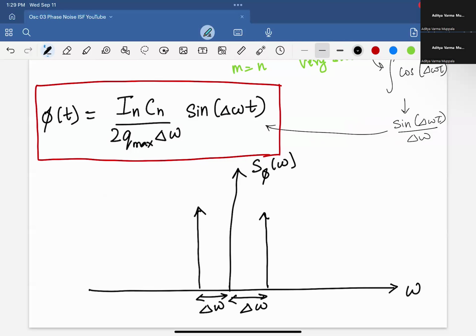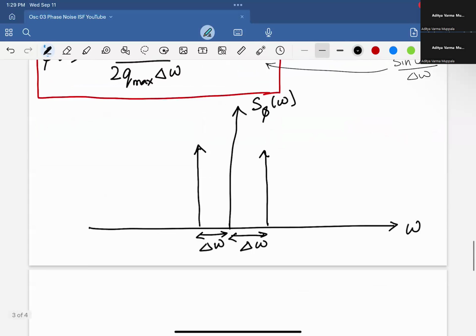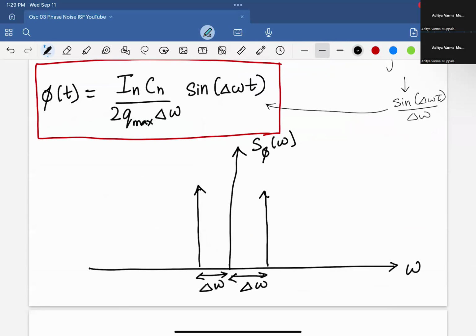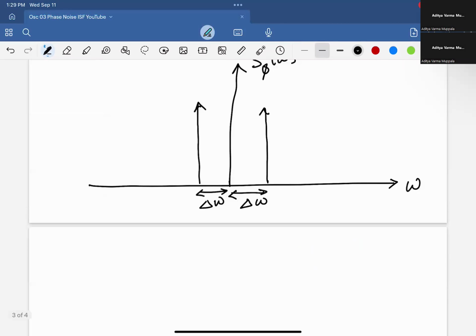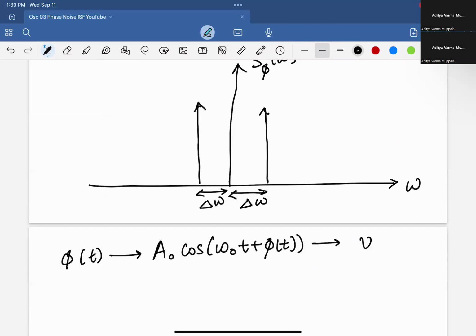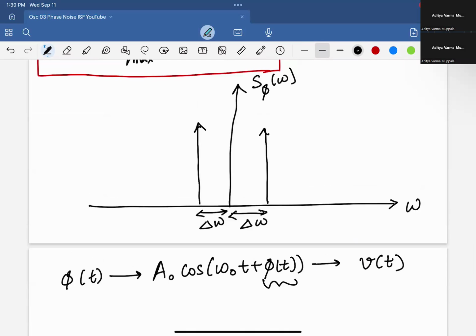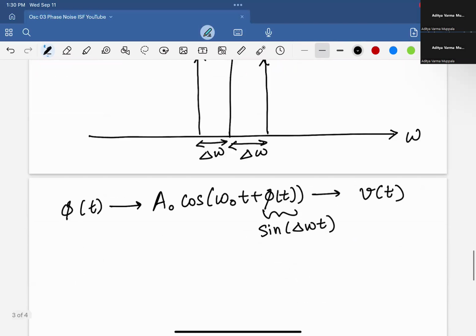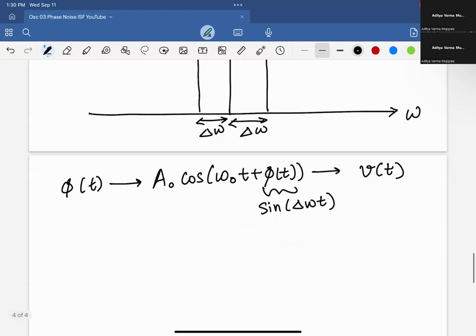All right. So essentially now what we're doing is we have to feed this, let's say for simplicity, into phi of t. We feed that into some A naught cosine omega naught t plus phi of t. And that gives us the v of t, right? Okay, so we know that this now takes the form of sine delta omega t, right? So it's essentially just phase modulation, right? And we know that when we do phase modulation, it essentially just creates...